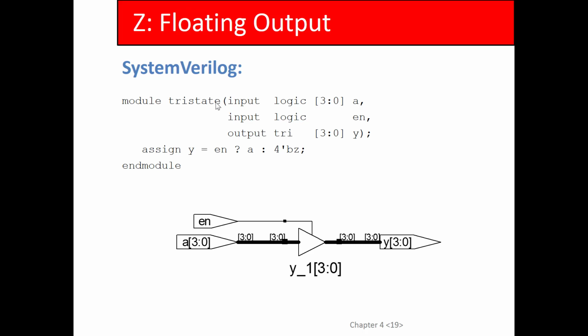Because if you put 4'b1, it's not going to put 4 ones. It's going to put 3 zeros and a 1. But for 4'bZ, Z is special in this case. It's going to put 4 Z's in here, right? Or you could just play it safe and explicitly type out 4 Z's. You guys with me?